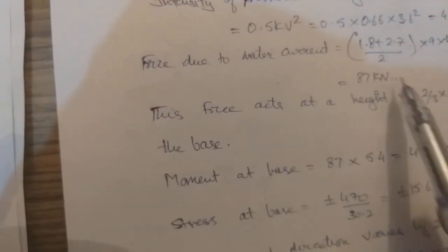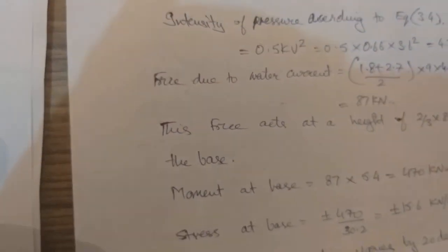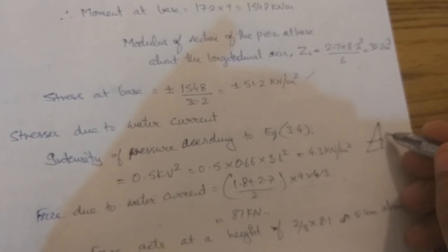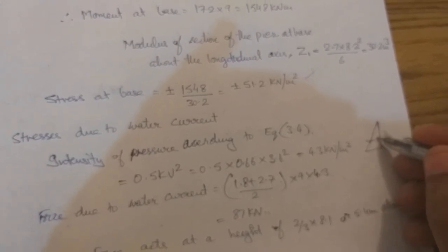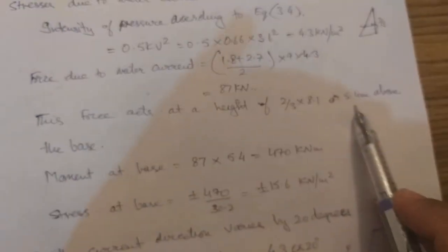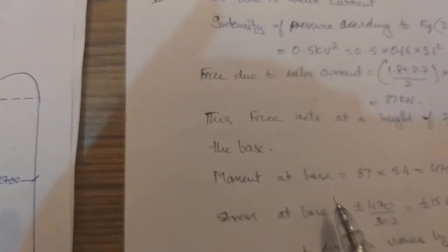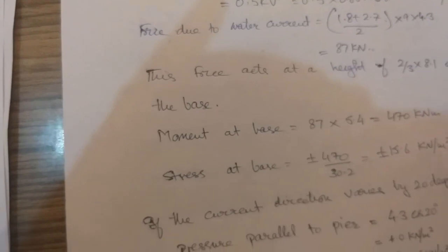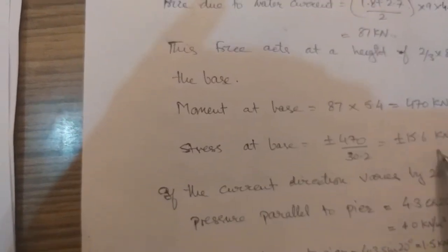And this force is going to act at 2 by 3. It is something like this. This is a triangular distribution, so it is going to act at 2 by 3, the center of gravity of the triangle. So this force is going to act at 5.4 meter above the base, and this force is 87. 87 into 5.4 comes out to be 470 kilonewton meters, and this gives me a stress of 15.6 kilonewton per meter